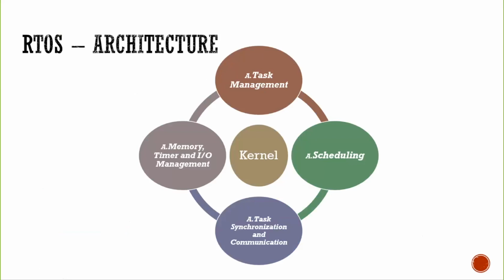There are different types of kernels typically used in RTOS. One is the monolithic kernel. The kernel covers all the components in a system that includes hardware, IPC, which is inter-process communication, file system, drivers, CPU processing, etc. These systems are highly effective on devices of single processors since they do not need many context switches, which is the procedure when a CPU changes between tasks or processes without conflict.